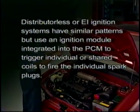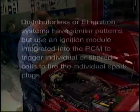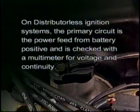Distributorless or EI ignition systems have similar patterns but use an ignition module integrated into the PCM to trigger individual or shared coils to fire the individual spark plugs. EI systems also use a camshaft position sensor to determine when the cylinders are at top dead center. Initial ignition timing is not adjustable on most EI-equipped vehicles as it is a function of the PCM software. On distributorless ignition systems, the primary circuit is the power feed from battery positive and is checked with a multimeter for voltage and continuity.